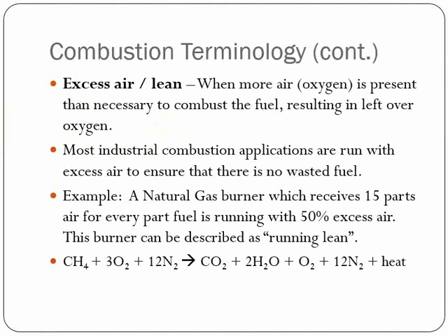When we start introducing additional air into the equation, a lot of times we'll refer to this as excess air or lean combustion. So most industrial process heater applications run with excess air. This is in an effort to ensure that there is no wasted fuel, as well as maintain a lower temperature of the flame and shape the flame to a desired shape, or affect the velocity of that flame exiting the